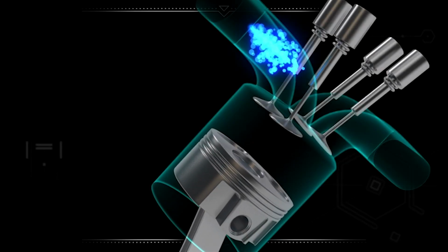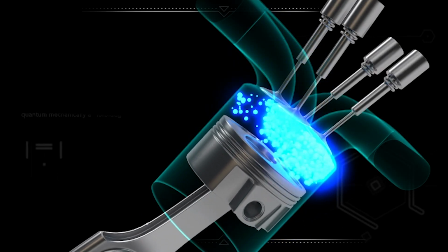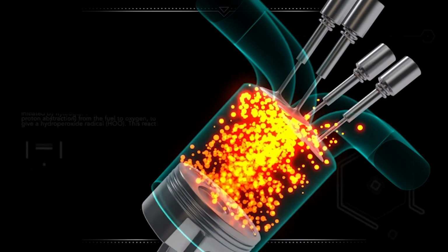There's a term, and I'm going to embarrass myself now because I should know this, but this is not a joke, what is engine knock? Is it quite literally something that sounds as if it's knocking? What engine knock is, we can go back to the four-stroke cycle, when you have that compression stroke of the fuel and air. So what I described earlier on was, as we get to top dead centre on that compression stroke, we spark the spark plug and you get a small flame kernel.